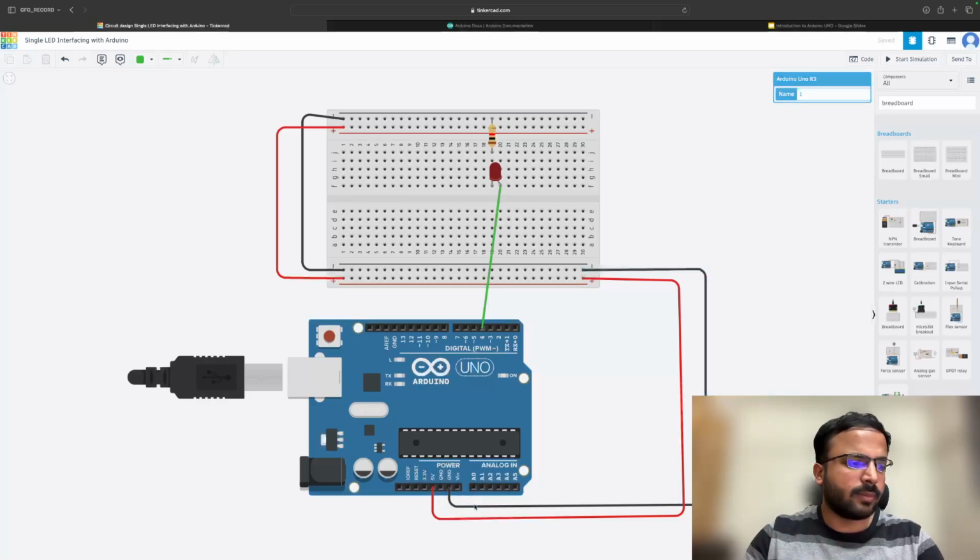Now this highlighted wire which you see, we connected to the minus, which means this will now be at 0 volt. Now this red one, if you see here it's written 5 volt. So this particular row, all of this will be at 5 volts. We also connected the black wire to this, so this minus row will again be at 0 volts. And in future we can use these outputs, these rows, these columns 1 to 30. So you have so many options to give power supplies and connect the peripherals.